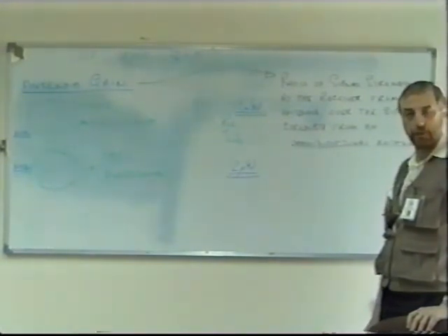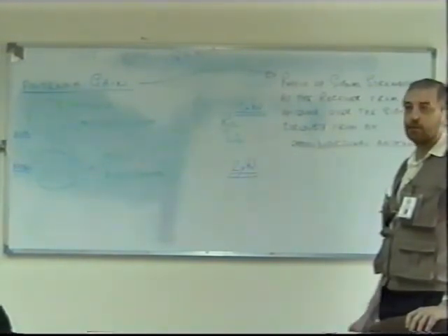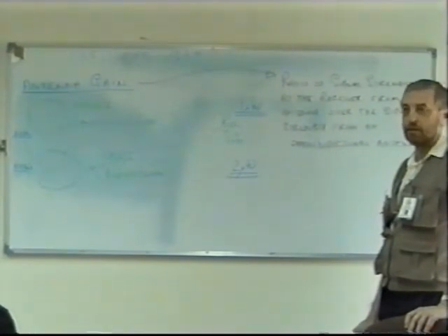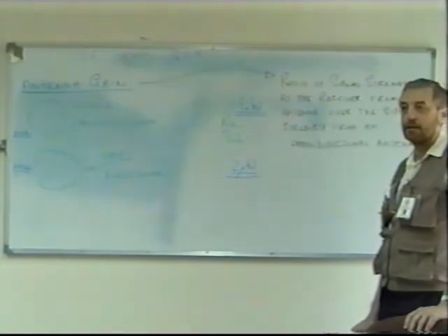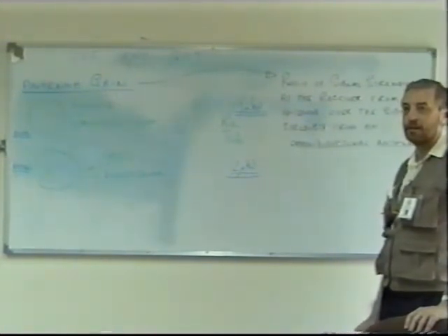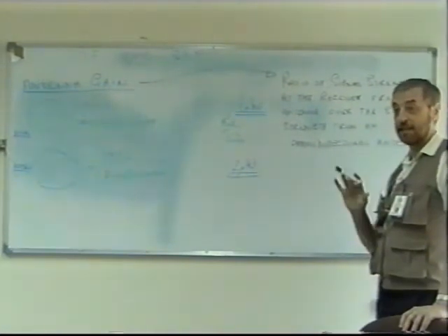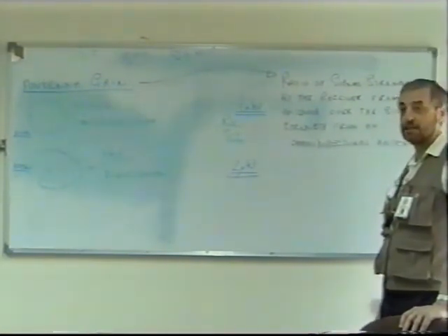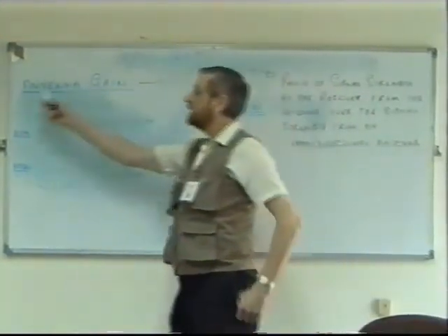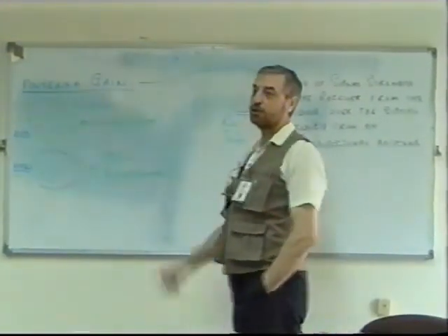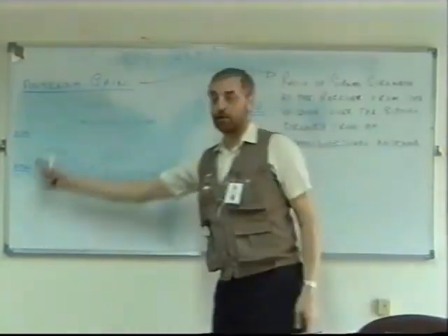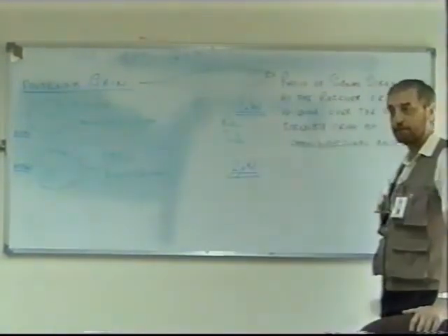What is the difference between different antennas: 0 dB, 3 dB, 6 dB? Well, which antenna would have 0 dB gain? The one that uses 1 watt, I think. No. It won't transmit nothing. By definition, if I said I have an antenna with 0 dB gain, what type of antenna is it? Remember, the antenna gain has nothing to do with power input and power output. It is to do with the shape of the radiation diagram produced by the antenna. That's what it is. 0 dB?